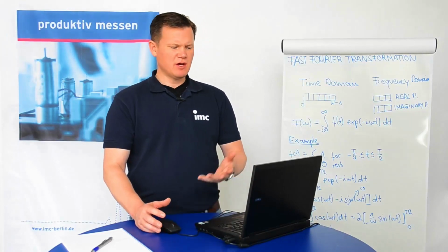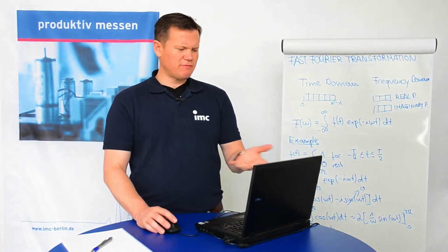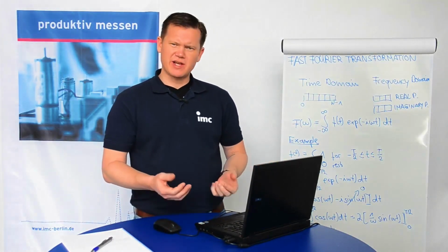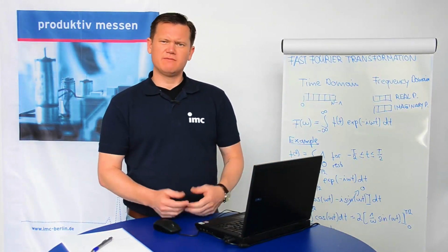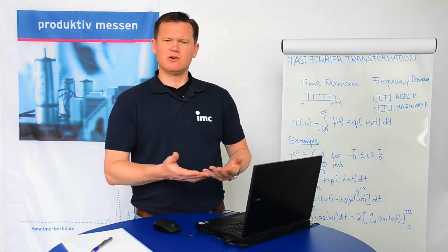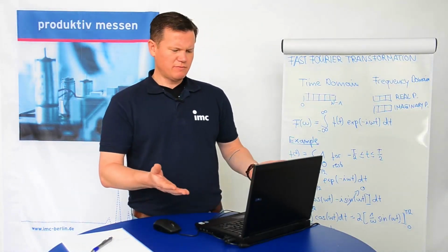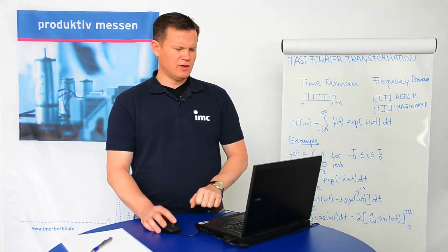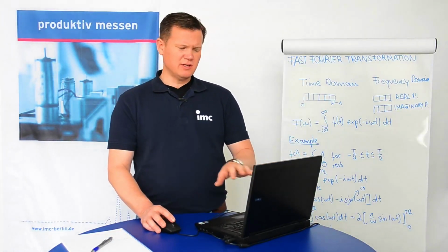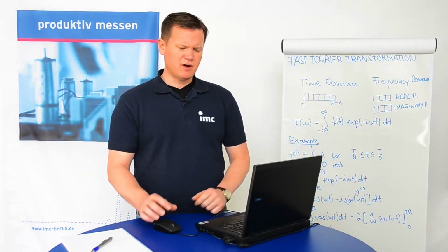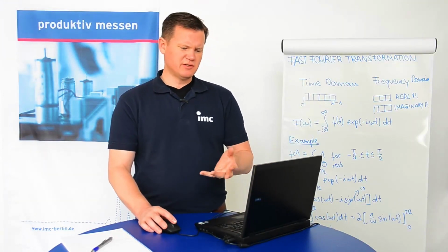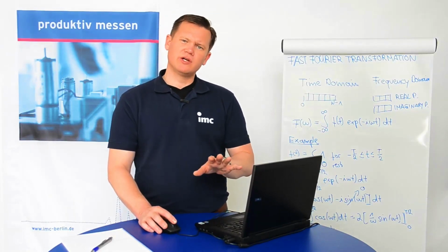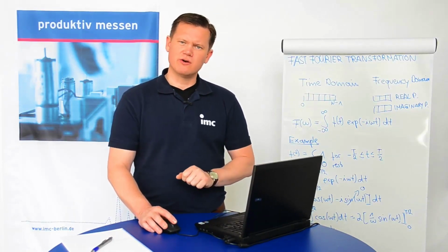In today's session, I would like to show you how you can load different file formats in IMC Famos. In addition to the standard DAT and RAW formats, a variety of other formats are also supported. With the help of import filters, these formats can be easily loaded into the software. For importing ASCII and Excel files, IMC Famos offers an additional assistant where you're able to specify all the relevant settings. This is what we're going to look at today, so let's go ahead and get started.